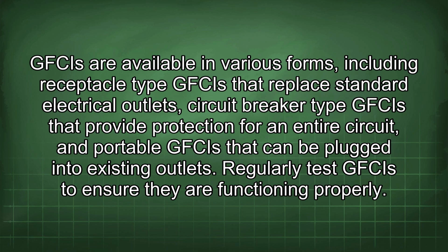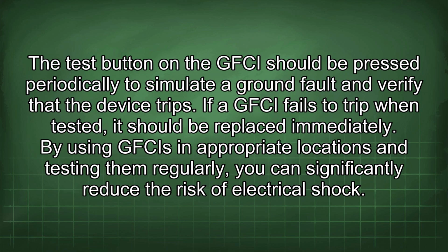Regularly test GFCIs to ensure they are functioning properly. The test button on the GFCI should be pressed periodically to simulate a ground fault and verify that the device trips. If a GFCI fails to trip when tested, it should be replaced immediately. By using GFCIs in appropriate locations and testing them regularly, you can significantly reduce the risk of electrical shock.